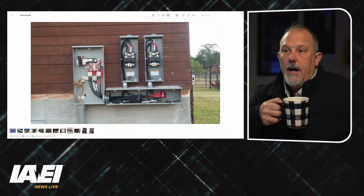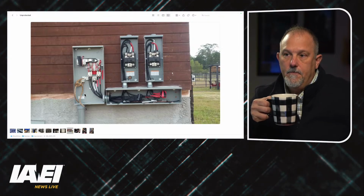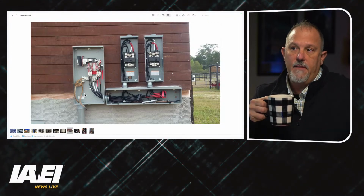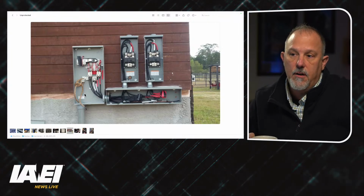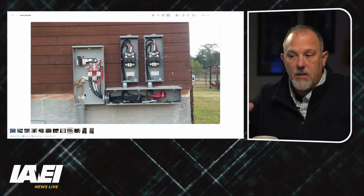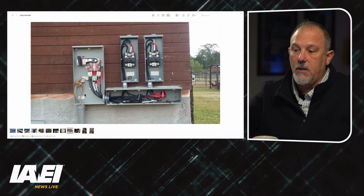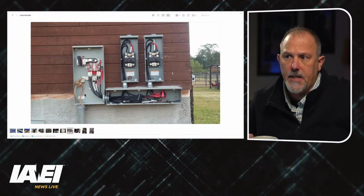I hit the meter socket, still unprotected. Meter socket, still unprotected from short circuits, right? So I would arguably have overload protection for those conductors, because overloads all stay in the circuit. I could have overload protection just because I am in series with an overcurrent protective device.